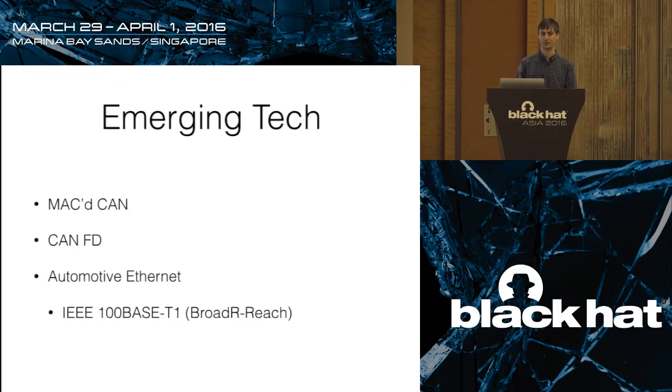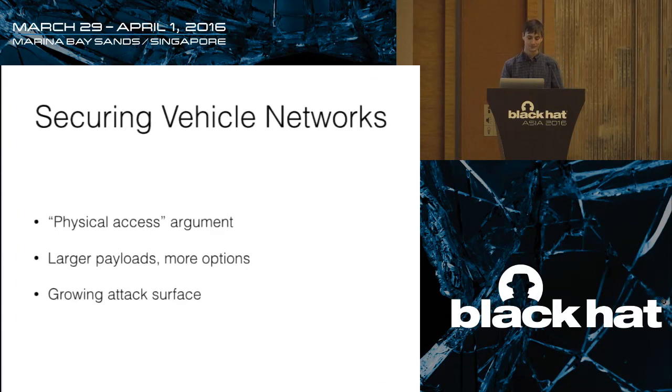In order to work with a computer, you're going to need a media converter. So that actually converts this 2-wire Ethernet to your traditional 4-wire that you'd find. This computer doesn't have an Ethernet port, but most do. You can plug that right in. Those media converters are still quite expensive, so that's one new place where it's like, hey, that would be a useful thing to have, low-cost media converters. And also, we'll have to start looking at the protocols they use on Ethernet.